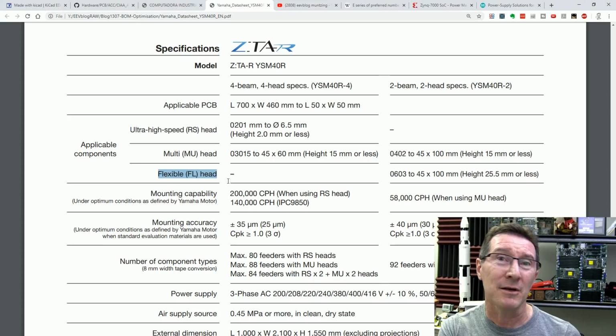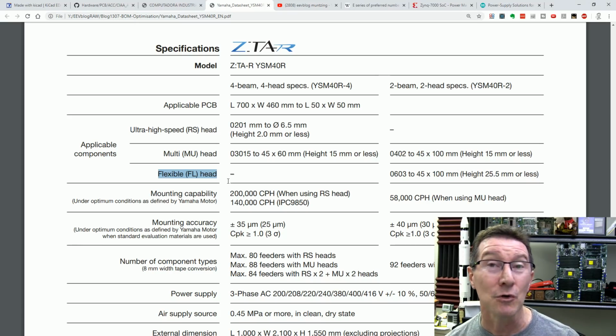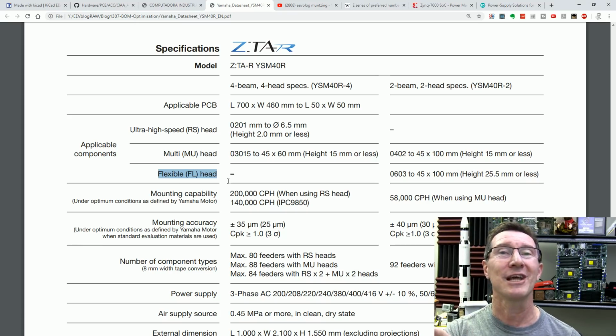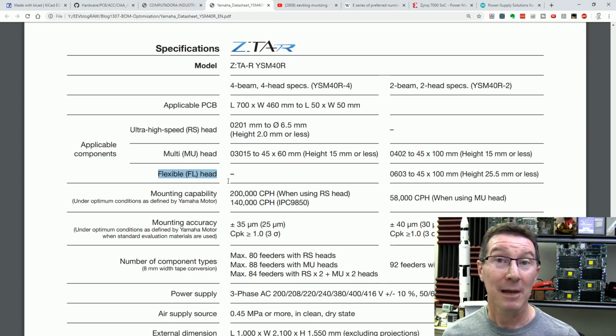They might be limited to 0603. They might be able to do 0402 for you, but there's actually going to be a lot of wastage. So your manufacturer might tell you, allow 5% or 10% for wastage, especially on smaller parts. And especially if you're using semiconductors, or chips, real tiny little packages, they might actually be expensive little devices, or really high precision resistors, for example.